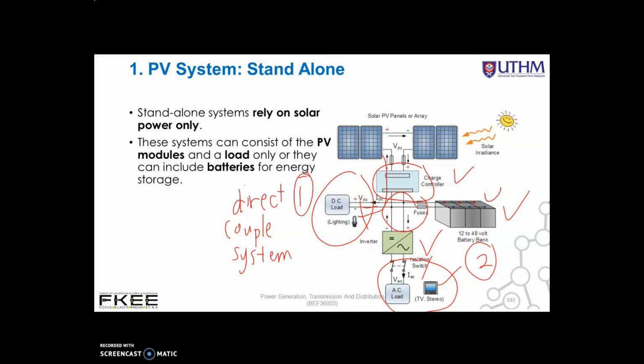First is the batteries. Batteries are an important element in any stand-alone PV system, but can be optional depending upon the design. Batteries are used to store the solar produced electricity for nighttime or emergency use during the day. Depending upon the solar array configuration, battery banks can be of 12 volts, 24 volts, or 48 volts, and also many hundreds of amperes in total.